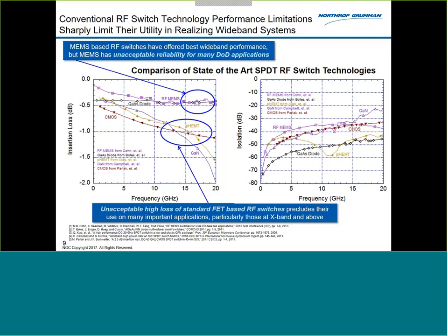So as I was saying, you have these low loss technologies that we really like. We'd like to have that kind of low loss. But then we have the FET technologies. Those all have a significant loss. So what you can see for broadband switches, we're getting over a dB of loss. And now remember, as I said, in a system you might have 60 of these switches. So 1 dB, okay, it might not matter, particularly if it's not on the front end. But I suddenly have 60 of these switches. That's 60 dB of gain that I have to make up in the system. And so you're talking about a lot of additional power to make up for that, and the linearity impact becomes quite significant. So, yeah, please.